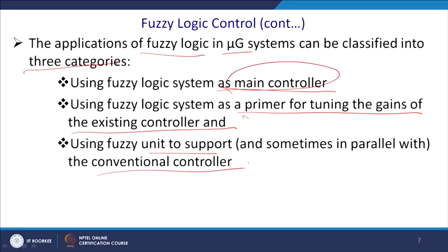So, you have to put it in parallel, and whichever gives the best results, you will take it. You may not discard the PI controller, because you have conventional wisdom on it. You take the juice from the PI controller. Once you see that it has more overshoot, because ultimately it boils down to the second order system, its settling time is more, and you cannot do anything.